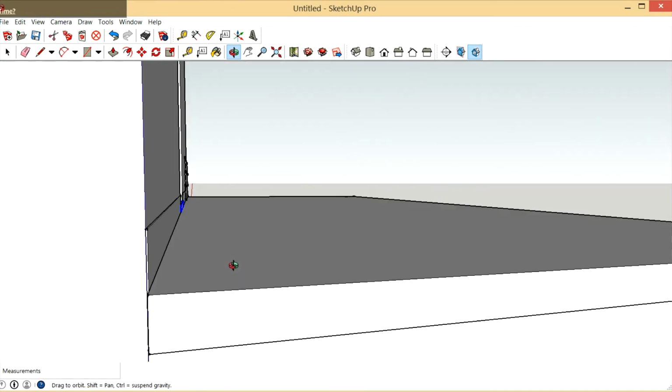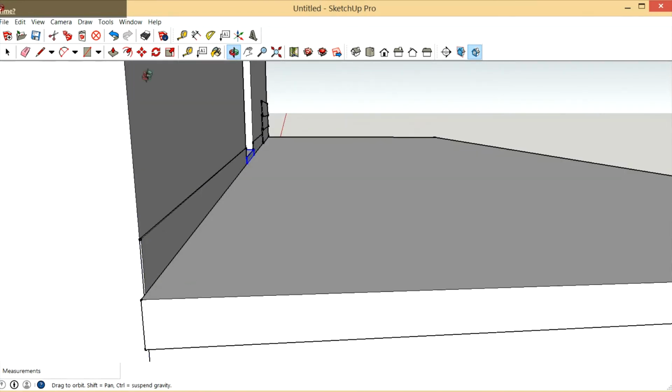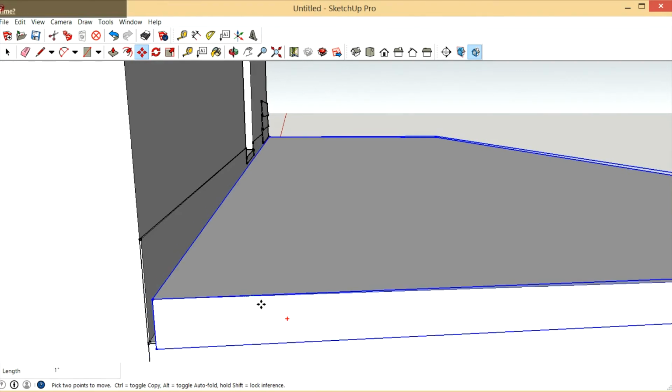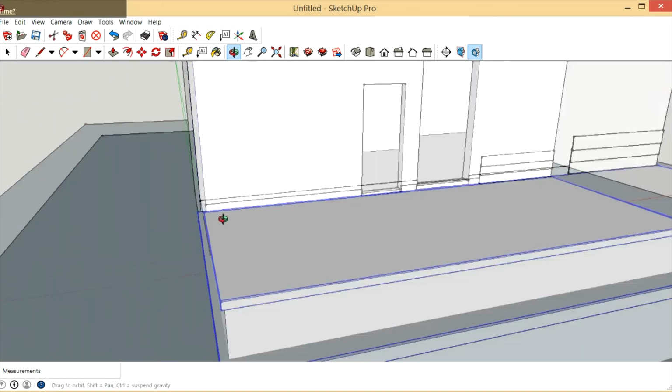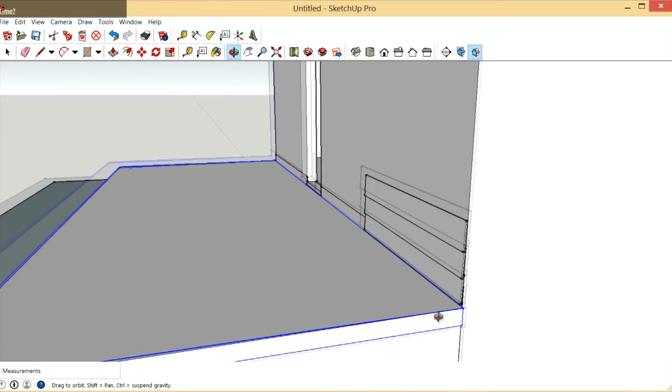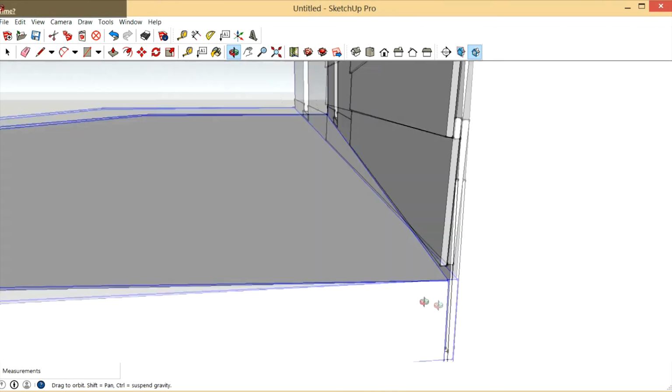use an asphalt impregnated expansion joint to bring this slab off of the house about a half-inch. And then there's this zip cap that you can use for that.